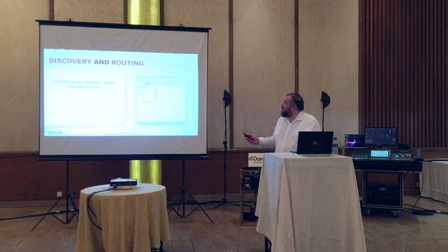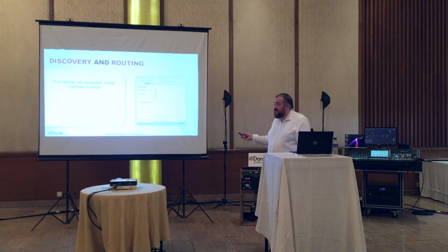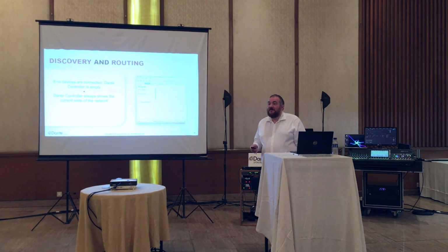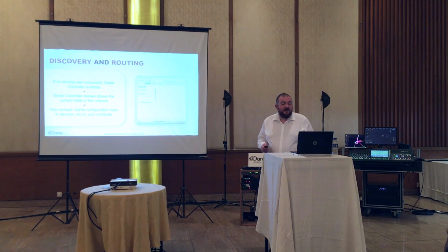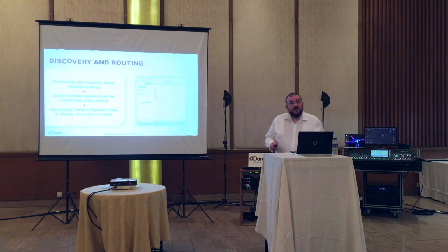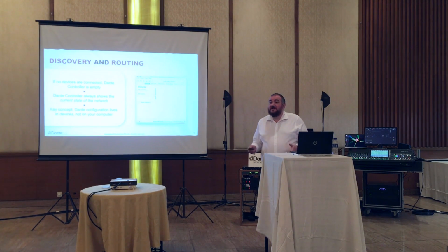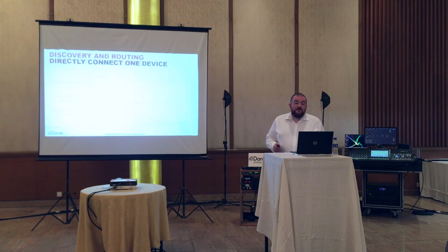So if no devices are connected to a Dante network, Dante Controller is empty. Dante Controller always shows the current state of the network, so it's a real-time view. And the key concept here is that the Dante configuration lives in the devices, not in your computer. So you don't need to have Dante Controller connected. You can also have multiple Dante Controllers connected to the same network perfectly safely as well.